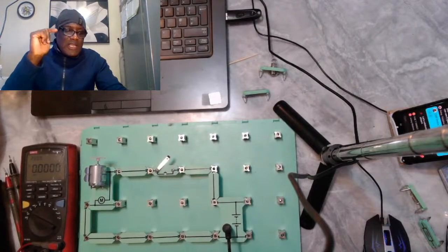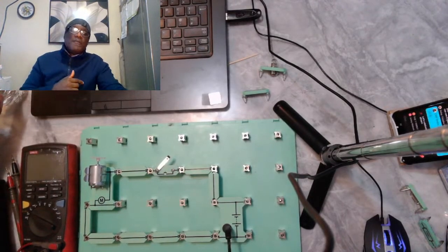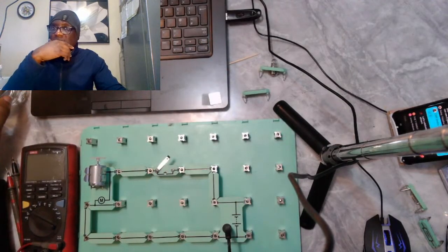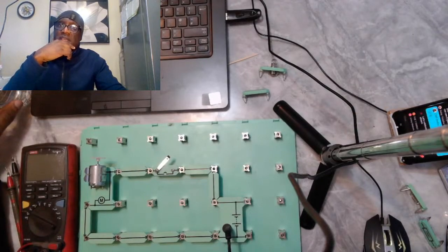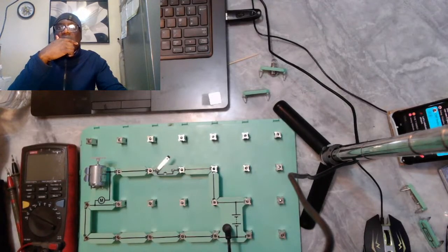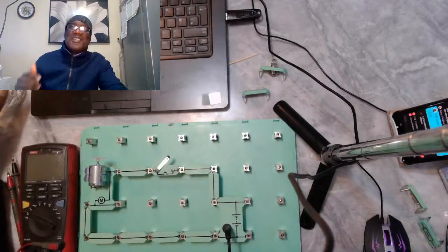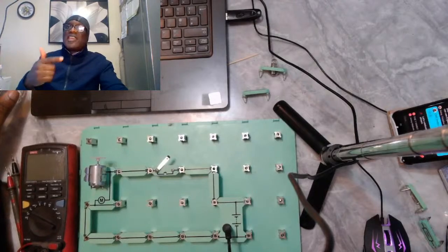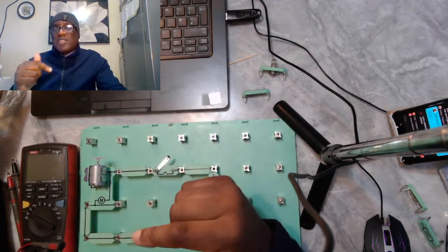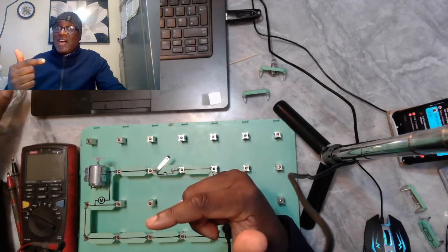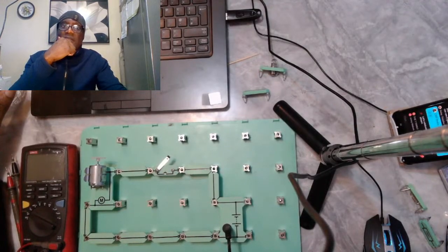I remember when I used to live in Africa, when I was in Zimbabwe, before I knew about electrics and stuff like that, I would see technicians sometimes go and get a bigger fuse and put a bigger fuse. It can work to a certain extent, but you'll find that the circuit will start overheating, because now there's too much current flowing in that circuit. It will start overheating, and if that happens, you might cause a fire. Never ever fit a bigger fuse.